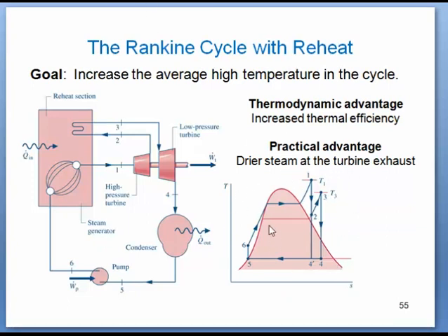So you can see from here, with increased boiler pressure and with the reheat cycle, this much extra work we are gaining, which leads to the increase in cycle efficiency. One more advantage of reheating the steam is that point 4 dash, which was in a wetter condition, shifted to the right.